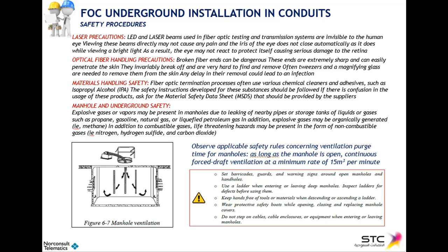So this requires a doctor procedure, and you can easily get infected if not treated. So please be careful with that as well. You are also supposed to handle some materials for fiber cleaning, such as isopropyl alcohol, that may irritate the skin. So please wear gloves as much as possible and always follow the manufacturer's instructions.